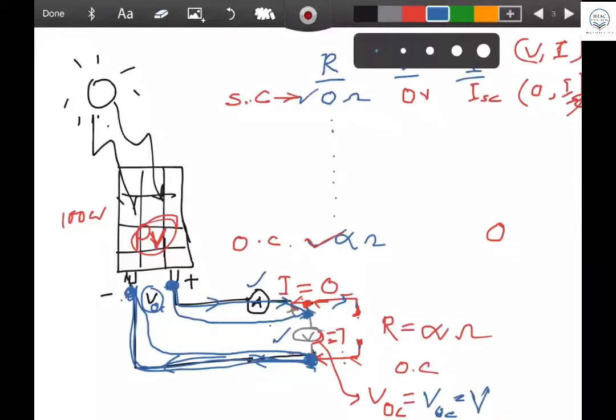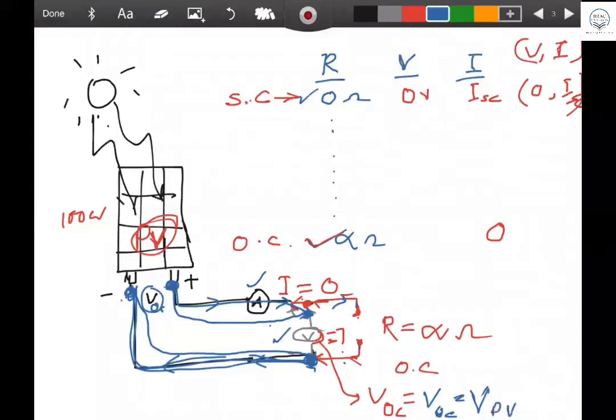In this case, we are going to get the PV panel, so I'm just writing PV. But what happens then? The voltage here, the PV panel voltage or battery voltage, if it is a 12-volt battery, if it's a 5-volt battery, comes straight away to that value here. So in the general case you are writing V open circuit voltage, which you get at this terminal when R is infinity, when it is open circuit. So the point is coming here, the VOC and 0, on the x-axis, y-axis.